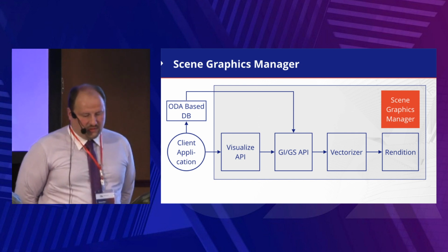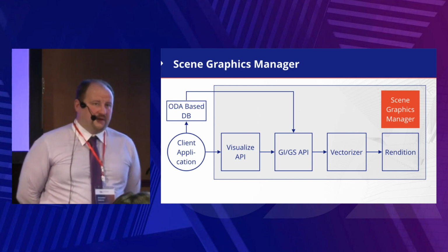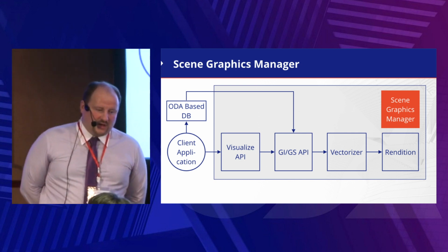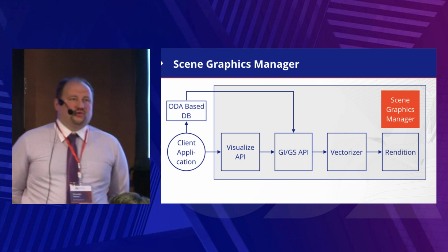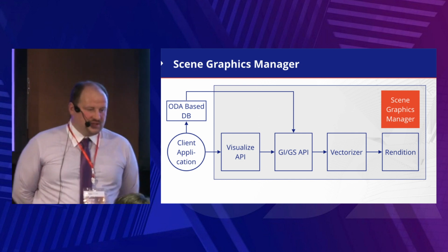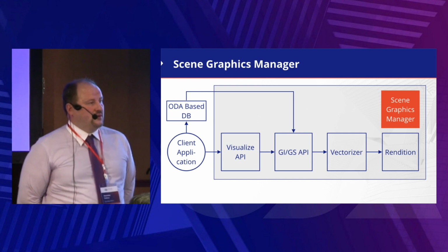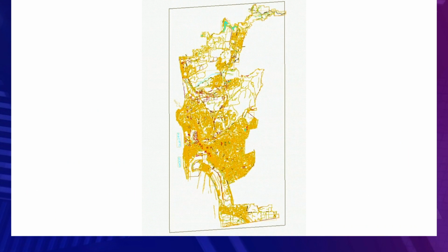This layer is called Thin Graphics Manager. The Thin Graphics Manager finds compatible graphic streams and merges them into graphic stream unions. On the next iteration, the graphic stream unions are merged with each other, and the procedure continues until there are no compatible unions anymore.